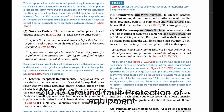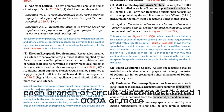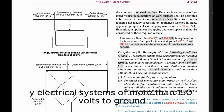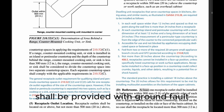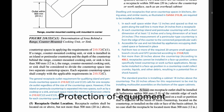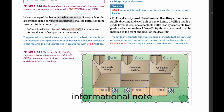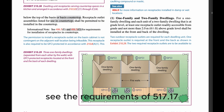210.13 Ground-fault protection of equipment. Each branch circuit disconnect rated 1000 A or more and installed on solidly grounded wye electrical systems of more than 150 volts to ground, but not exceeding 600 volts phase-to-phase, shall be provided with ground-fault protection of equipment in accordance with the provisions of 230.95. Informational Note: For buildings that contain healthcare occupancies, see the requirements of 517.17.